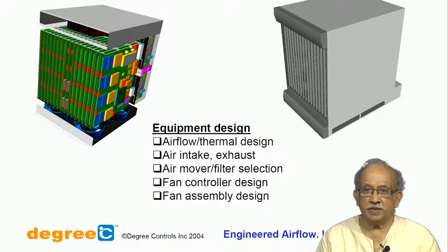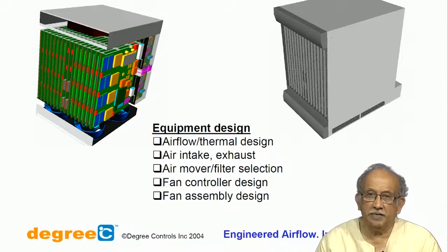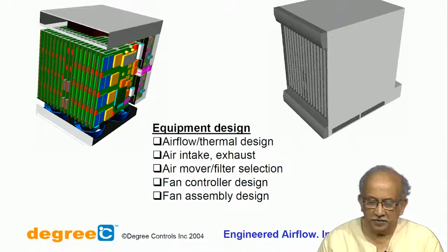Since we are all automobile people, we have got used to a little bit of automobile, all of you I am sure have come across the air filter inside your car or your motorbike. So, first thing you will suspect is probably the air filter, take it out and dust it off, or better still you can probably pressure clean it and so on.